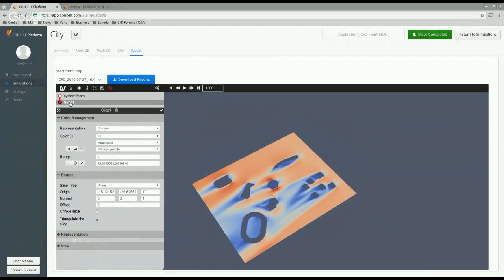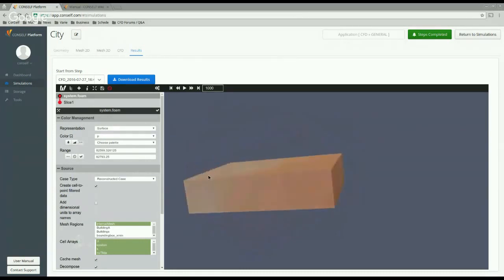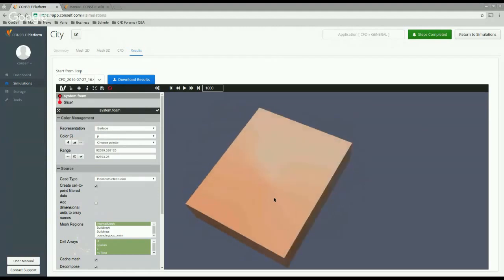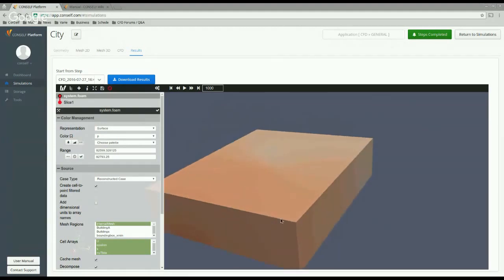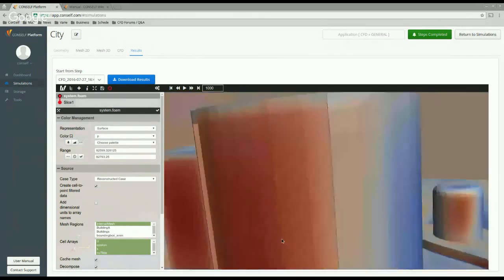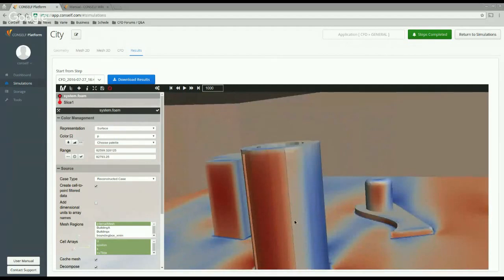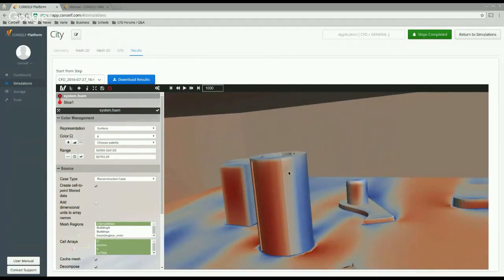and as you can see, we have a flow that encounter our buildings, then we have the wake behind our buildings. So let's take a look at the pressure over our buildings instead of the field around them. So we can zoom inside our bounding box, and you will see we have obviously those buildings that are facing the wind directly, they will have a peak load.